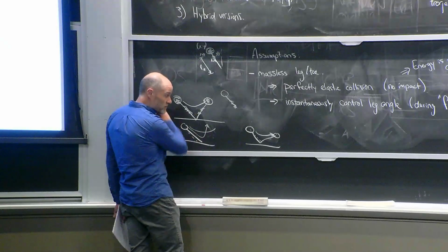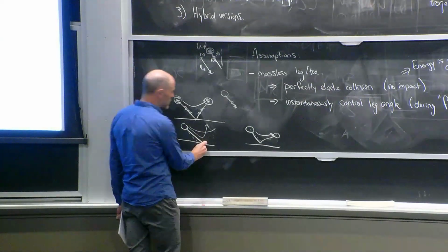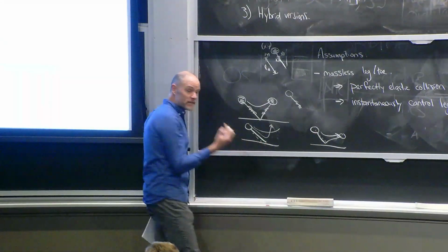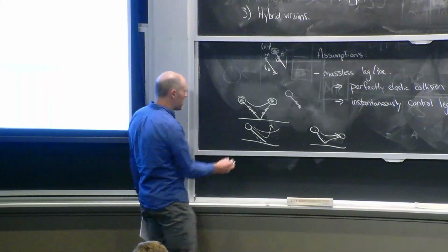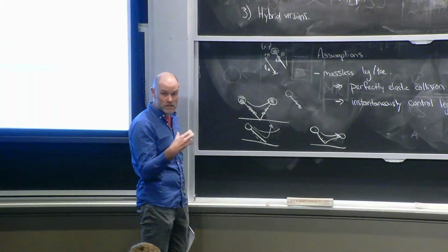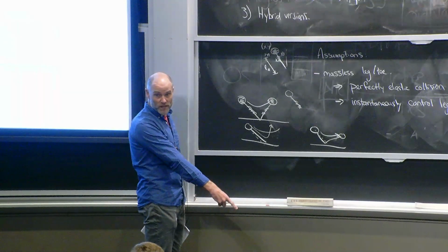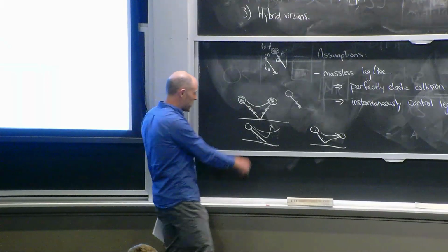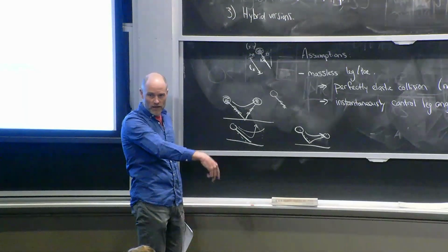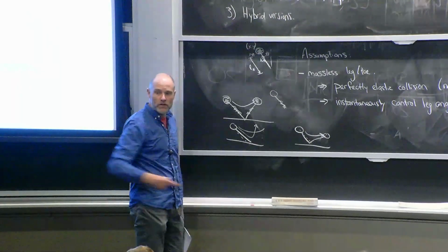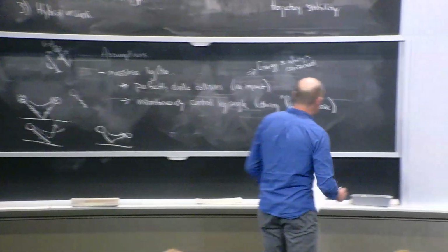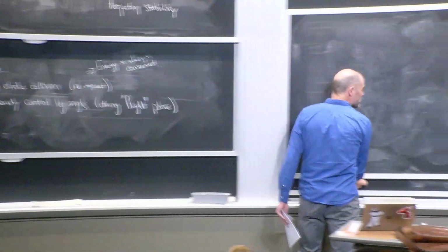The way we're going to do control is to think about foot placement as a control strategy, a decision that is effectively made once per hop. When I'm in the air, I think about where I am currently compared to my desired hopping height and desired hopping speed, and I make a discrete choice: what is my touchdown angle of my leg? Then I go through this motion, find myself at a new hopping height and hopping speed, and once again make a discrete choice. Once per period, I get to make a control decision. So let's think about how that plays out with our basic toolkit.